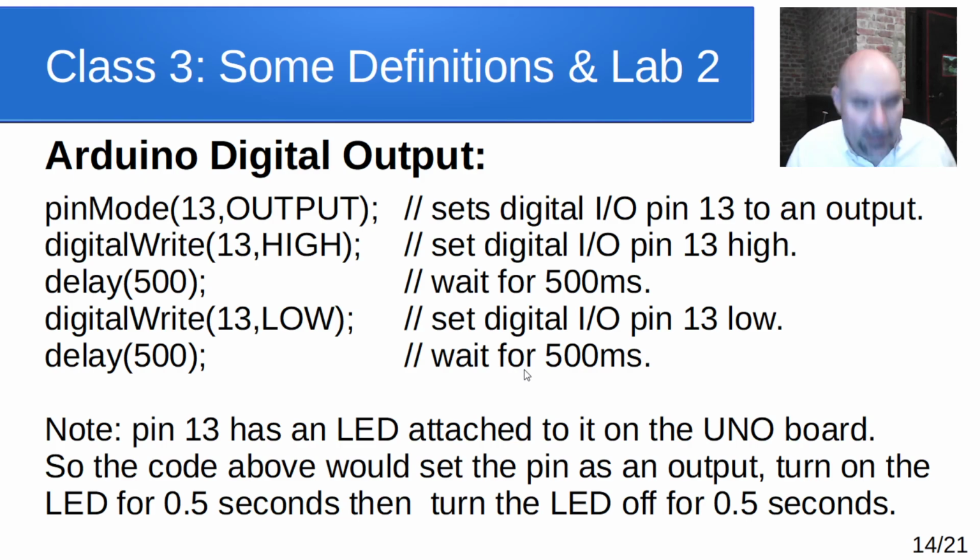Okay, a little bit of the code. Again, this library is part of the Arduino library stuff that's built in. You don't have to include anything. You don't have to do anything. Like I said, the Arduino environment kind of abstracts away or hides some of that detail, so we don't have to worry about it. But the first one is pinMode. So, for example, I could say pinMode 13 OUTPUT. That sets pin 13, which is a digital I/O, as an output. They default to input. So this sets pin 13 as an output.